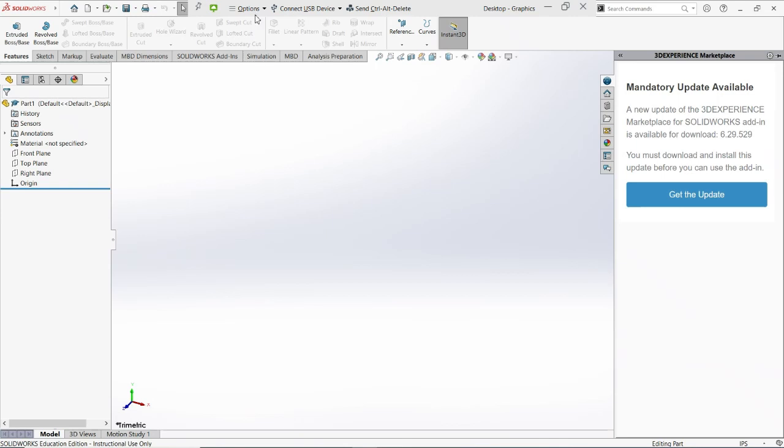Alrighty, so now that we've got our initial screen, there are so many buttons. Don't worry about what each of them do as of yet. There's one process that you're going to follow throughout all of CAD, and this is where our base shape, simple shape idea comes in. First thing you do is you're going to make a two-dimensional sketch, and then you are going to create a feature from that two-dimensional sketch that brings it into 3D.